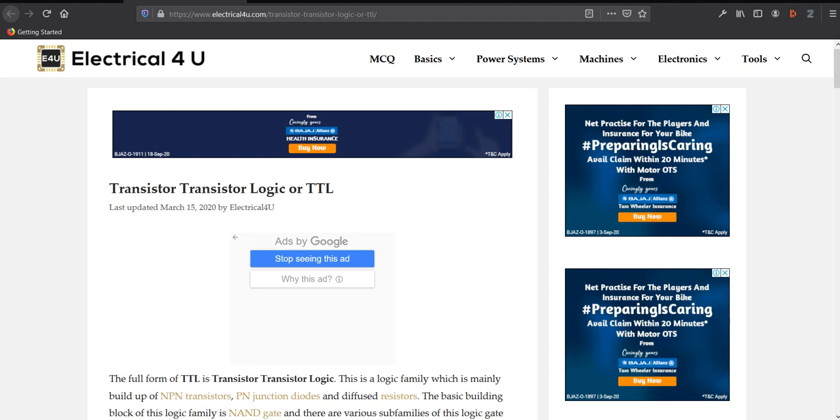Let's see what happens. During the positive edge of the clock, X is high, right? So where will it take the input from now? It will take from D. D is taken, so the output will be low initially, logic 0. And then X is going low, so the preset value is 0, so the output will go to 0. It will continue 0.